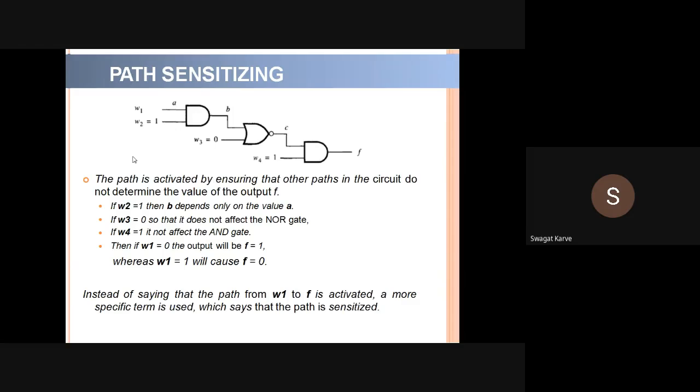And what is our rule? We have to consider one wire, right? Consider that it is connected to a logic 0. The same wire next time, consider that it is connected to a logic 1. Carry out this check. Then again consider the next path or connection, permanently stuck at logic 0. Then again consider it permanently stuck at logic 1. Again check the conditions, right?